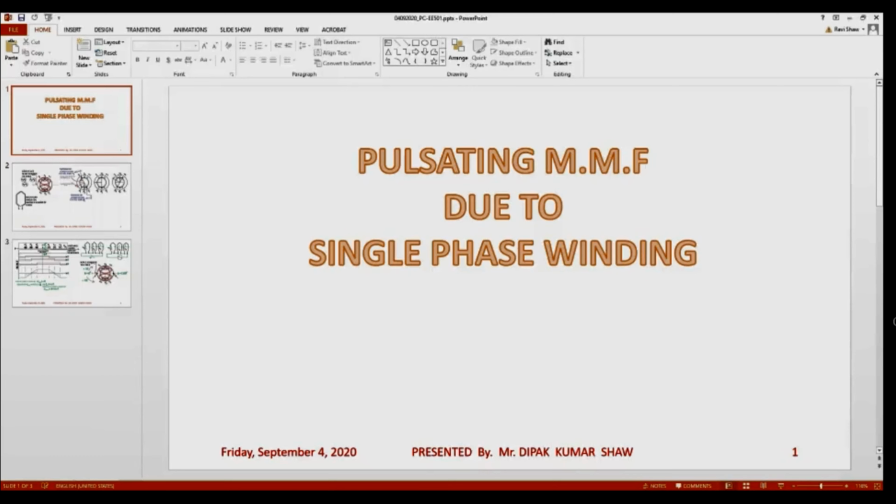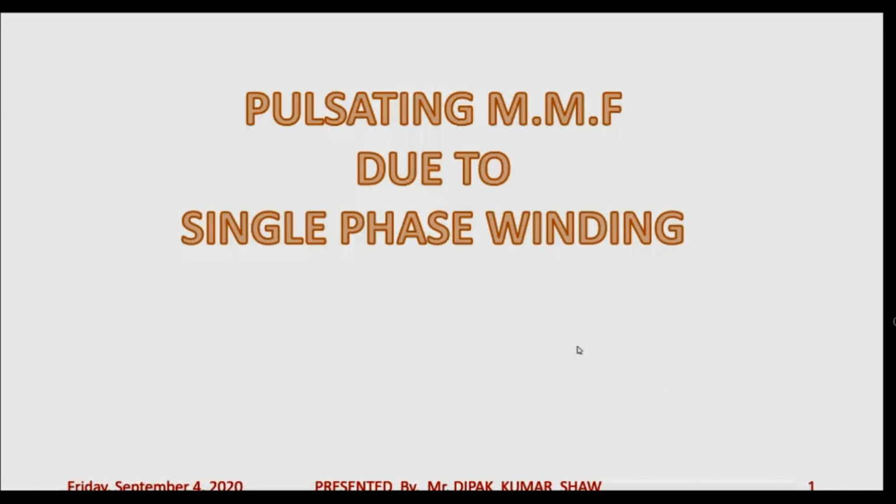So the topic of today's discussion will be pulsating MMF due to single phase winding. This term pulsating MMF you will encounter when you study single phase induction motor. So what is the meaning of this word pulsating MMF? Pulsating means which is changing with time. The magnitude or the amplitude of that quantity is getting changed as the time passes on.